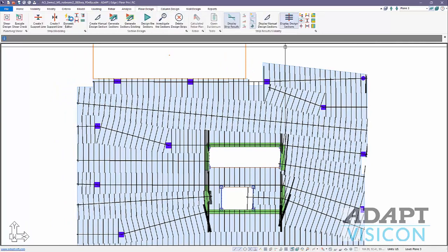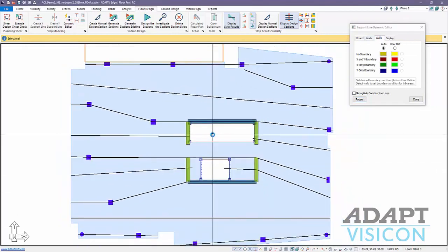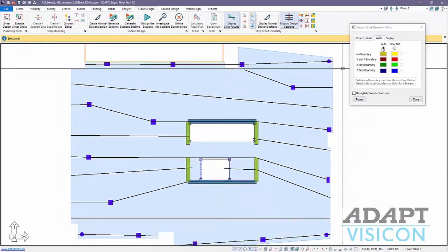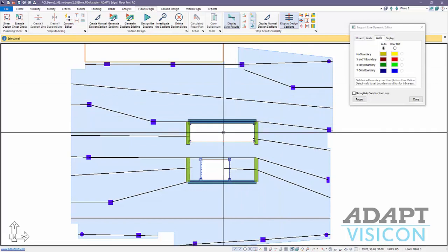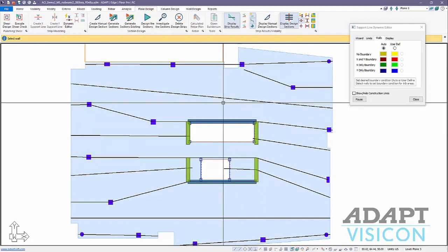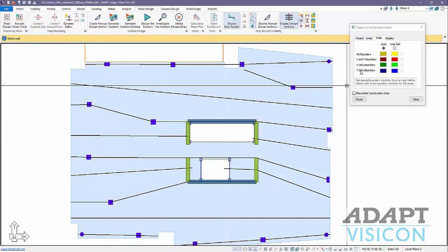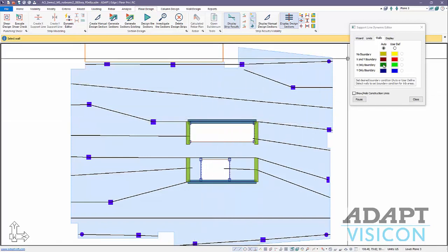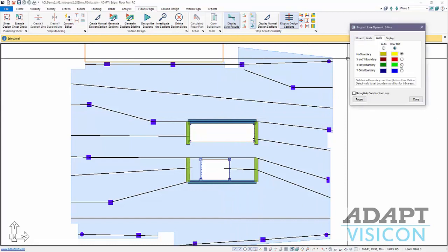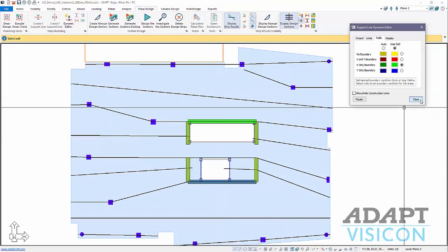Okay, coming back to the dynamic editor, the third option here is walls. How do we go about generating section cuts near walls? You can see that there's some auto options here that are already set. This is pertaining only to the wall as how it's defined in terms of a boundary for design strips. So for example, this line here says it's a Y only boundary. I want this to be an X boundary. If I change this, for example, to X boundary, I'll just do user defined. I'm going to go ahead and click on that wall as an X boundary, and I'll close it.